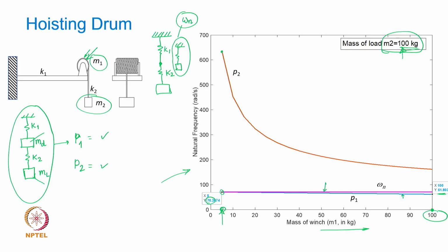Are you able to understand what is happening? We are changing the mass that we neglected, making it sizable compared to the other mass. Okay, when it happens, the second natural frequency keeps reducing, as you can see, and the gap between the two natural frequencies starts reducing. Okay,